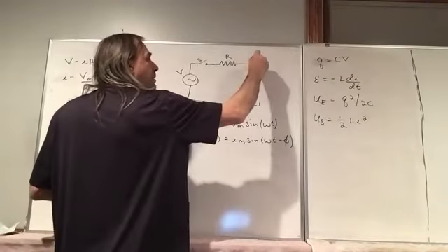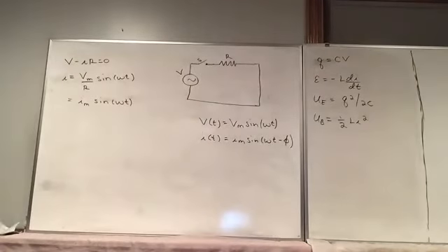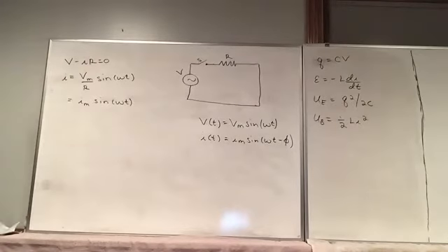So to start with, let's say we remove the capacitor and the inductor. So we just have a resistor, and using the loop rule, V for the battery, we have voltage drop across the resistor. So using the loop rule, we have V minus IR equals 0. And just solving for the current, that's trivial. So no problem there. And in this case, phi is 0.